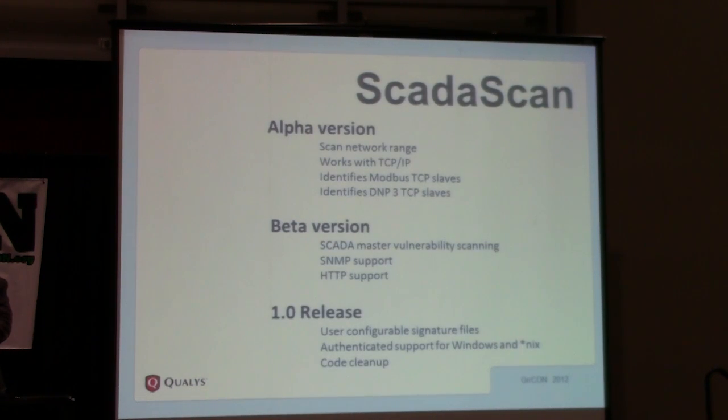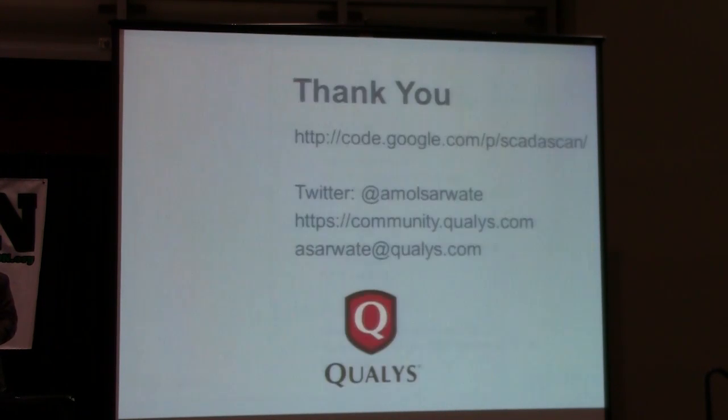This is a little bit of a roadmap of the SCADA Scan tool, which is currently in the alpha version. It supports Modbus and DNP3. In the beta version, what I plan to do is have some SCADA master vulnerabilities on it, and support for HTTP and SNMP. But in the final 1.0 version, what I really want is user configurable signatures, because no company, me, my company, or any other company, will ever be able to get their hands on all types of SCADA systems. So if it's a community-based thing where you could upload your own signatures to the tool, that would be fantastic, and that's the goal of the tool.